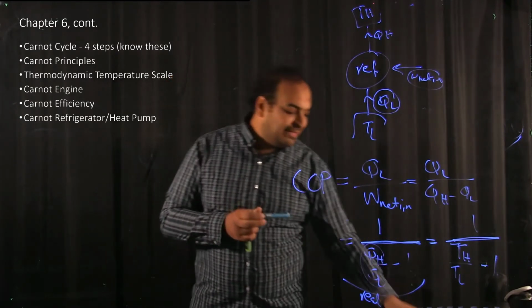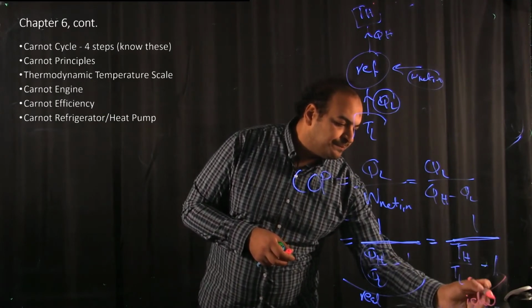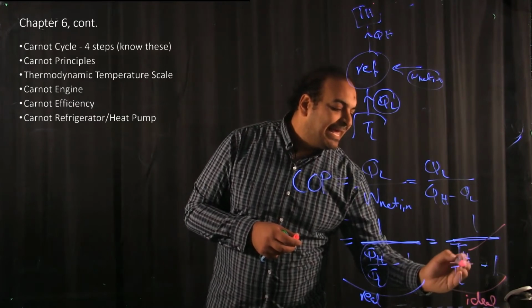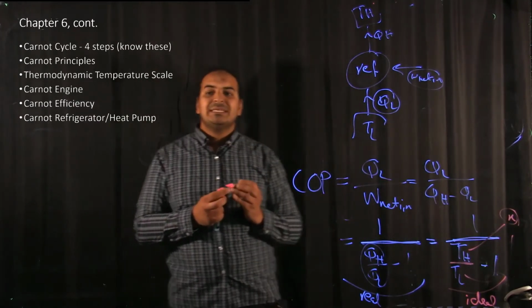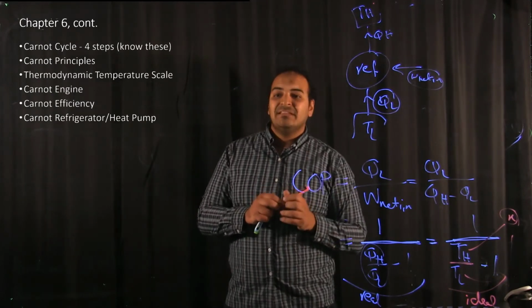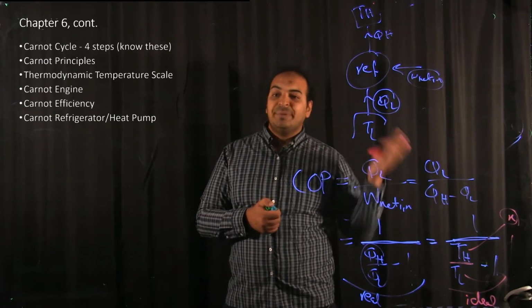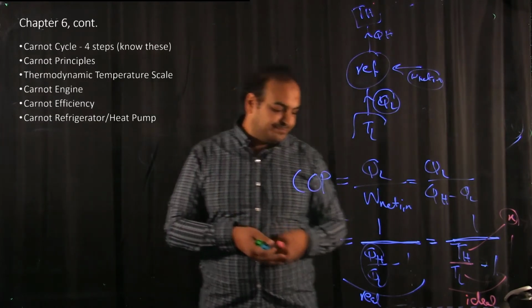Remember, this is only valid for ideal, Carnot. Also, this temperature should be in Kelvin. Do not substitute anything if you are talking about SI units, anything other than Kelvin: not Rankine, not Fahrenheit, not Celsius. If you are talking about the British units, it is Rankine, not Fahrenheit.